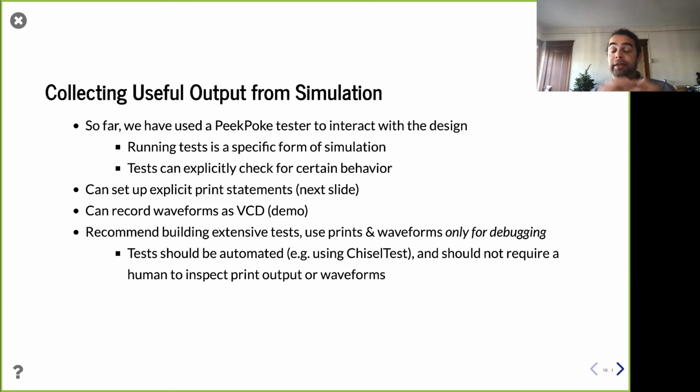You're going to rather want to simulate it once and go through it. So that's the beauty of a waveform: you run a simulation once, you get all the data once, and then as you have more questions, like, oh, I'm curious about the value of this signal at this time, you can just answer that from the same waveform. But depending on your style and what you're doing, you can use both in this class. I recommend using waveforms if you haven't before, just to play around with them.